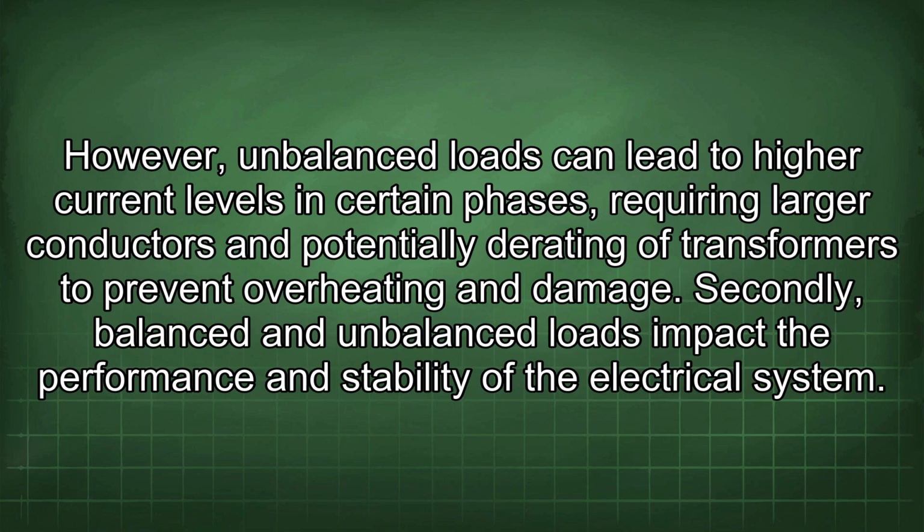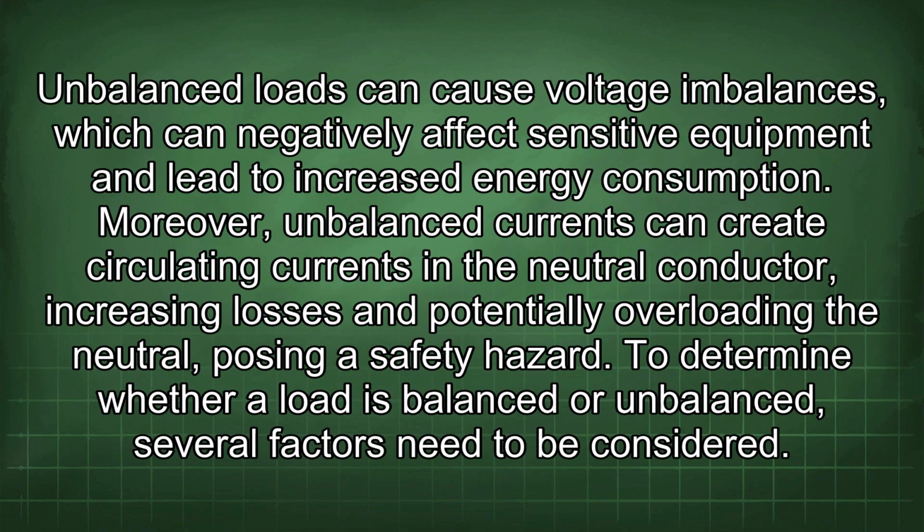Secondly, balanced and unbalanced loads impact the performance and stability of the electrical system. Imbalanced loads can cause voltage imbalances, which can negatively affect sensitive equipment and lead to increased energy consumption. Moreover, unbalanced currents can create circulating currents in the neutral conductor, increasing losses and potentially overloading the neutral, posing a safety hazard.